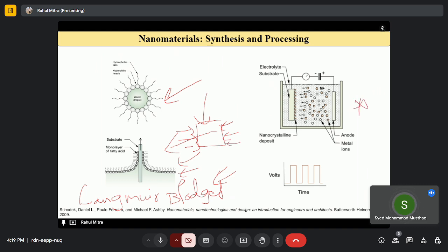And the next process is the electrodeposition process. In the electrodeposition process, we deposit nanofilms on our electrodes or substrate, and the main process that we follow is to form nanofilms instead of dendrites in the structure. So how do we produce nanofilms instead of columnar grains?